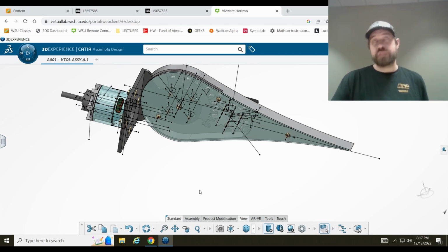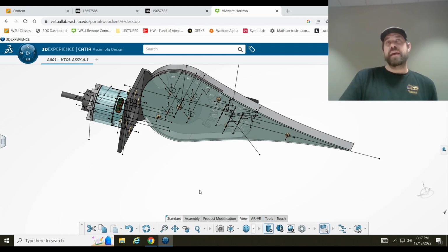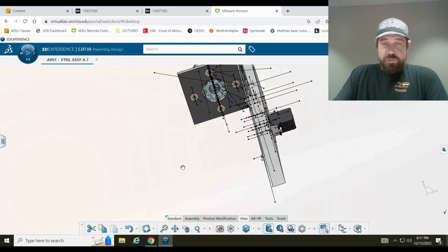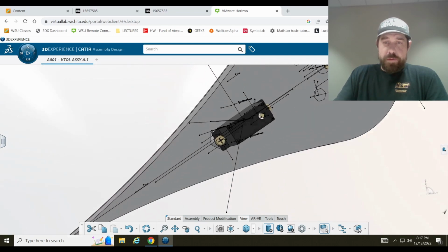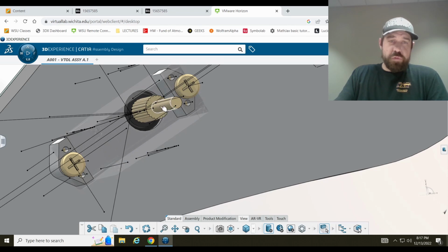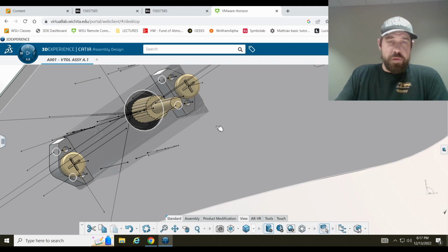It was usually a concentricity of an axis, which will lock on the angle between a line on each face, and a contact or an offset to hold it along that line at a certain position, and that will create a rigid connection. The ones that I didn't want to be rigid connections were the motor shaft inside the servo here. So the connection between the servo motor housing and the motor shaft is a revolute connection.